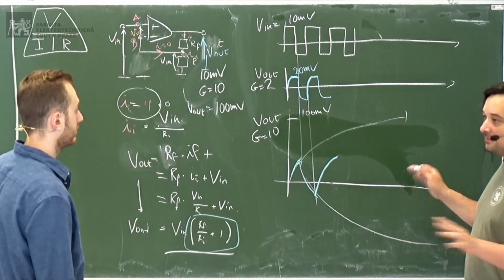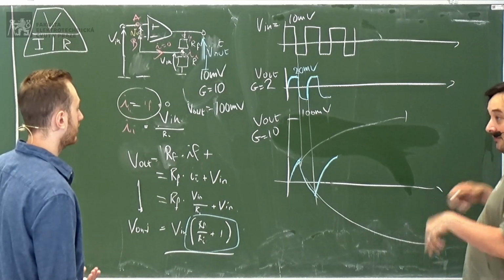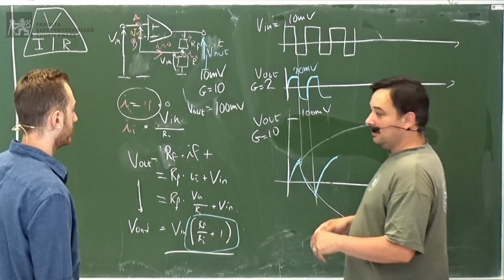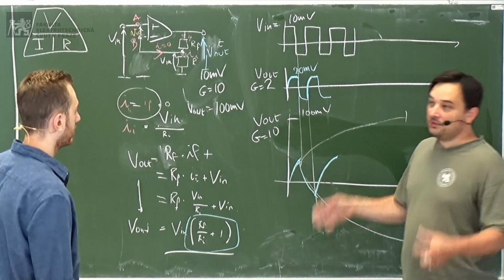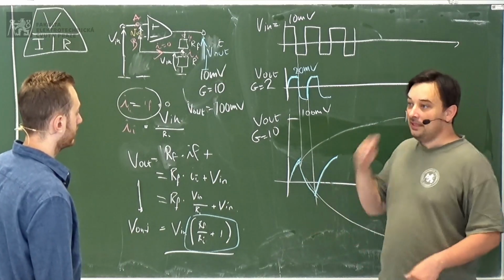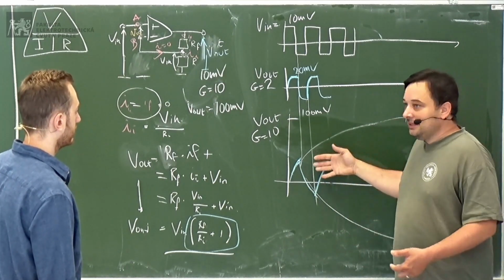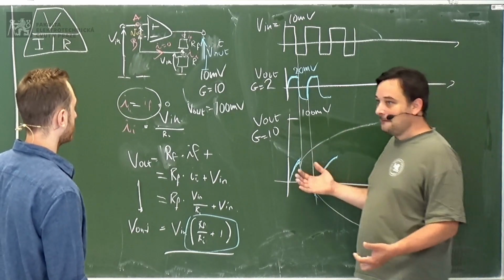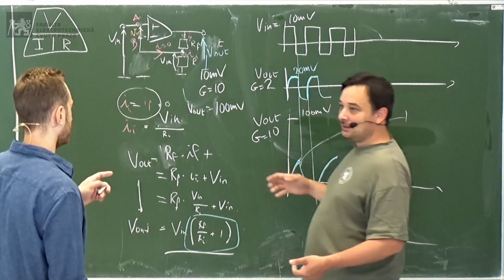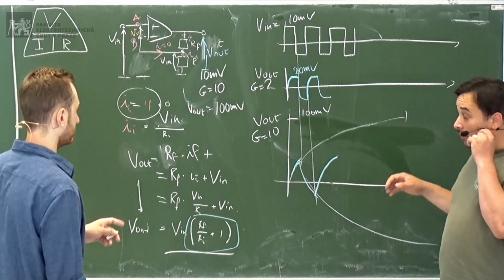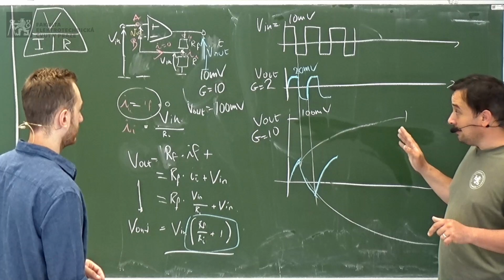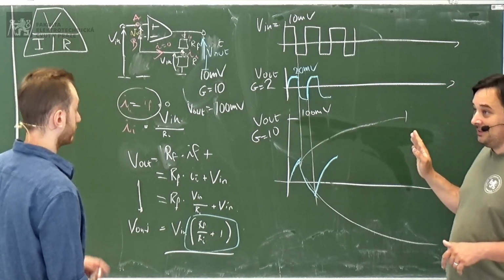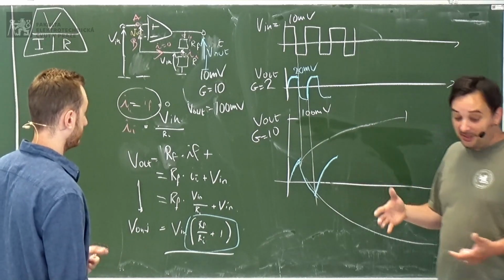There are a lot of things that can limit them, but inside you have an operational amplifier which amplifies the voltage you take, and the amplifier does not have infinite bandwidth. They are limited. This is not just the bandwidth, this is the slew rate. But the slew rate and the bandwidth are extremely connected.